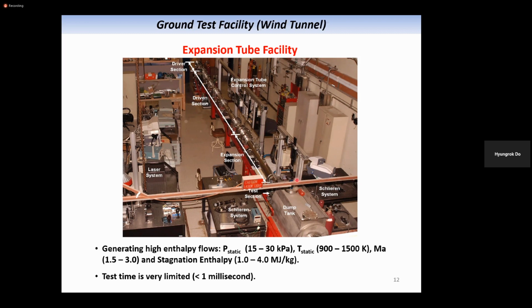And this expansion section and the driven section will be filled with the test gas. The test gas will be heated up by the shock wave. As you know, a shock wave increases the pressure and temperature simultaneously. So the test gas, which is stored in the driven section between the two diaphragms, will be heated up by the shock wave. And the shock wave is definitely moving at supersonic speeds. Although this is like tens of meters, it takes only milliseconds. So everything is happening within milliseconds.